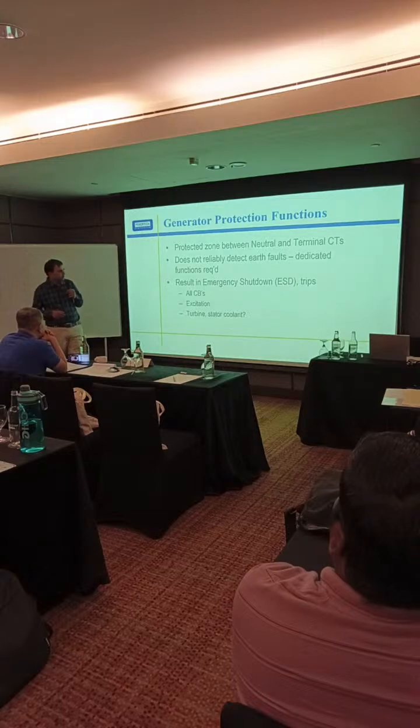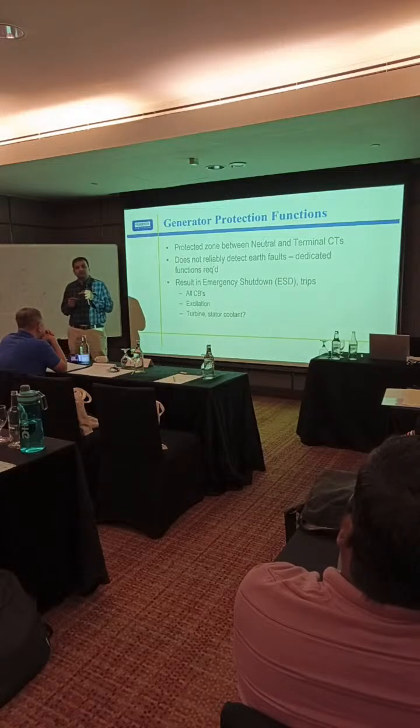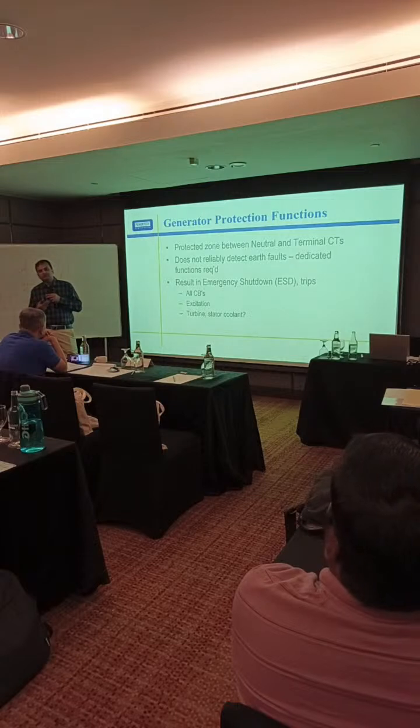That is why mostly these differential relays work for phase-to-phase type of faults. Maybe sometimes during a phase-to-ground fault, if it is not much current, then the differential current may not detect it.